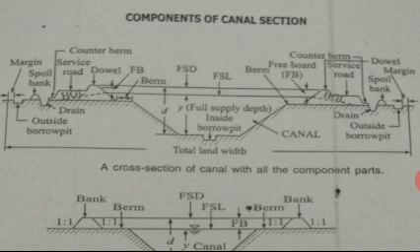The permanent land is the land which will be required permanently after the construction of the channel. The width of the permanent land is the distance between the outer toes of the banks of the canal plus a few meters up to about 1.5 meter on both sides for the construction of drain or for planting of shade line trees.